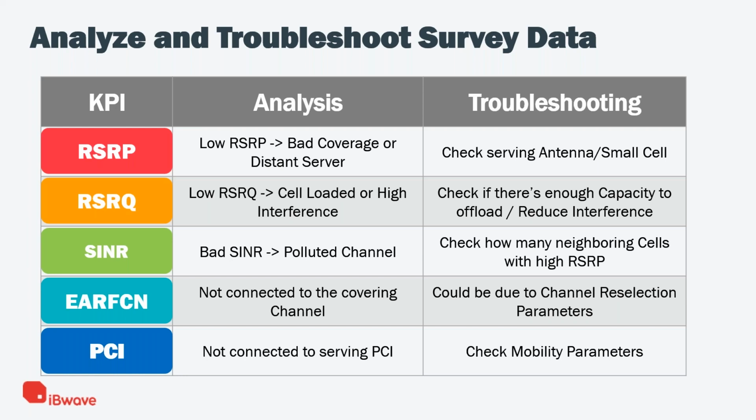It could happen. I've seen that in the past, and in this case, you would need a spectrum analyzer and track it down and just remove it. Since it's licensed spectrum, it's not like in Wi-Fi, when you have interference from a non-recognized device. Well, unless they are in your own control, your environment, your network, you might be able to shut them down. But in public space, you can't do anything about them, right? It's an unlicensed spectrum. But in LTE, almost all the time, it's a licensed spectrum. So you just call the regulators, and then they're going to shut down this interference.